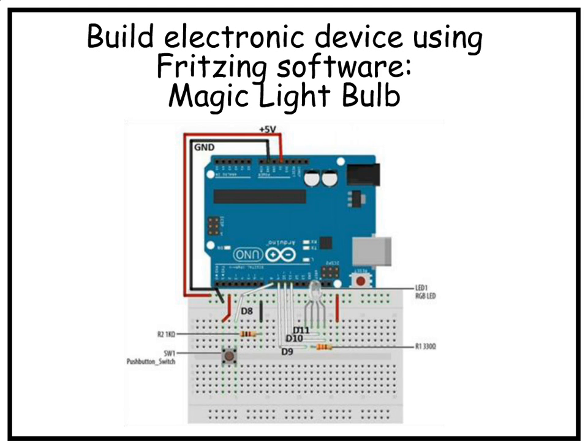Hope you guys can see this too. If you notice, this is a little mini breadboard. The kit, meaning the Arduino Microcontroller Pad, has a full-size breadboard. It's clear. I'm not an advocate for the clear board. Sometimes it confuses me when I'm wiring up a circuit, but some people like it because they can actually see how to lay their wires out. And also, the nice feature that I do like is it shows the construction of how the breadboard is built, so you can understand why these particular five little dots on the board are positioned the way they are, and how to really wire up a circuit without, say, creating a short circuit, meaning two devices that should not be connected, that will be considered a short circuit.